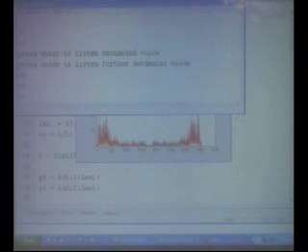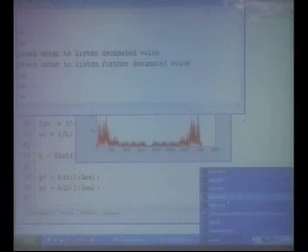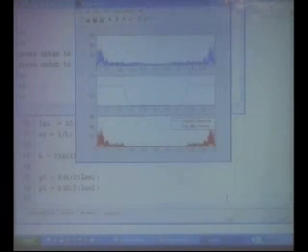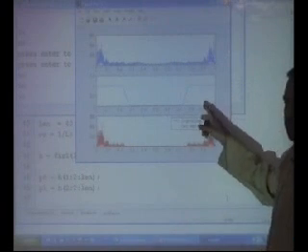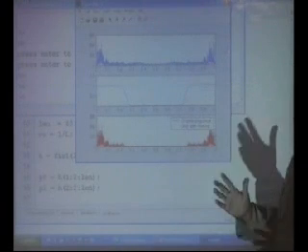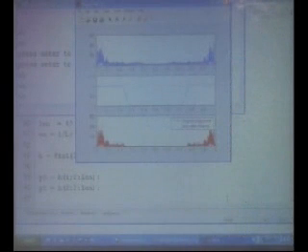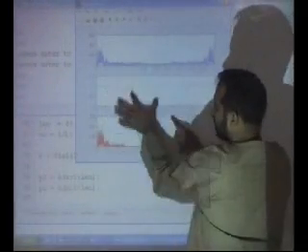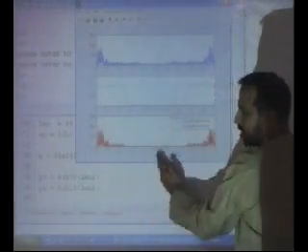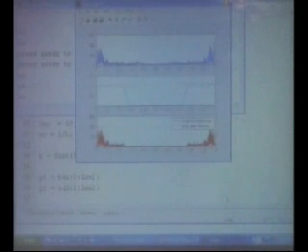So in this file I have actually passed the signal through a filter. This is what is done: before I decimate, first I clean it up. I say, okay, I really want to decimate because I don't want to support that higher sampling rate. So I use this filter, clean this part of the spectrum, and now cut it and move it. Though I am throwing away information, I am not aliasing at all. So I cut it down and then I move.